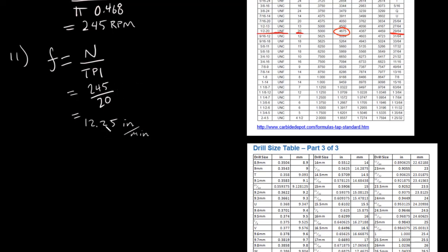But a CNC machine often can only, there is a limit to what you can program. And since this has to be perfectly divisible and keep all the decimal places, you need to play around with this number here so that you don't exceed the decimal places of the CNC machines.